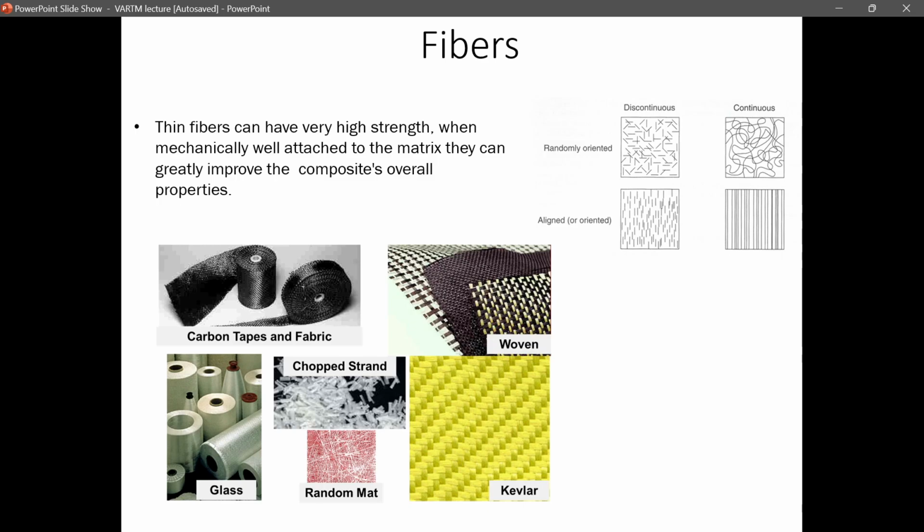You have to choose your fiber, and then you have to weave your fiber. There can be different patterns, right? And these different patterns are the thing that is going to determine the strength of your composite eventually. For example, this woven pattern here is not going to give you the strongest material, but its strength is not unidirectional. So it is strong in both directions, comparable to metals, but it's lighter than metal.